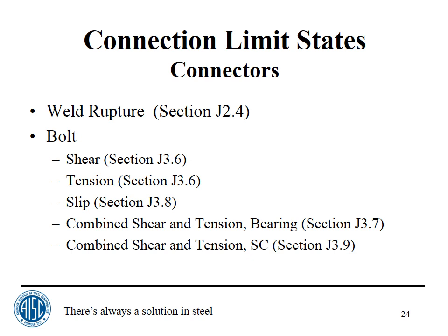One of the disadvantages of the tabs is that you've got bolts in single shear, so you might need more bolts. But we have found that the cost in the shop is more than offset by the savings in the field in the erection of this.